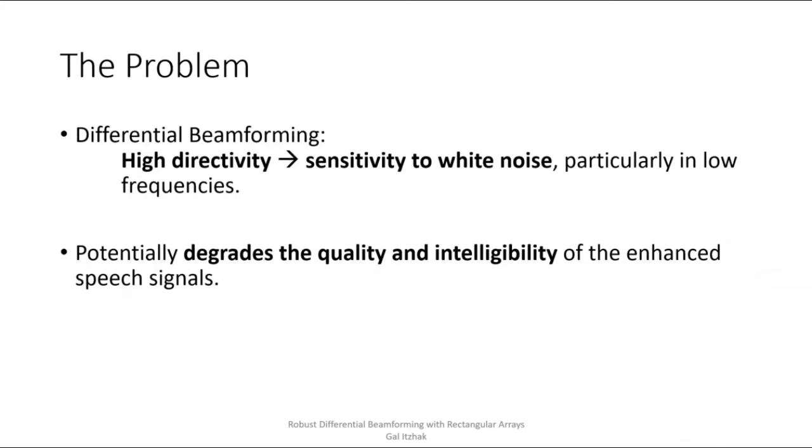So what's the problem? Well, it's well known that high directivity differential beamformers suffer from sensitivity to white noise. This problem is particularly severe in low frequencies and may result in a significant degradation in the quality as well as in the intelligibility of the enhanced speech. So it implies that we may be able to further enhance the speech signals by mitigating this sensitivity to white noise.